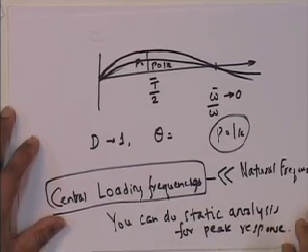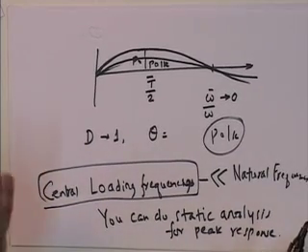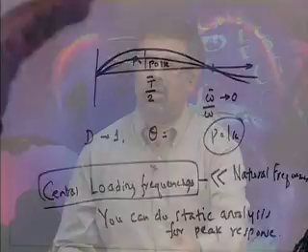Very, very important. In this particular case it is a harmonic load, so we know what the loading frequency is. But for any kind of loading, by performing some mathematical operations, you can get the central loading frequency, the loading frequencies in which the maximum energy of the load is.